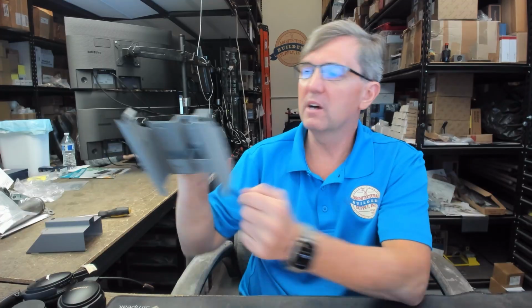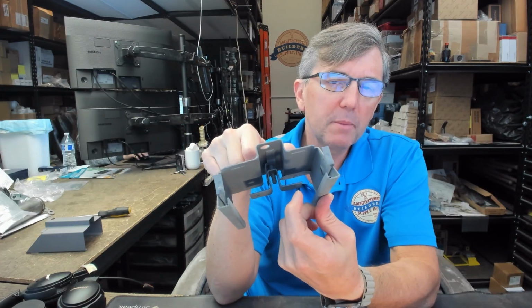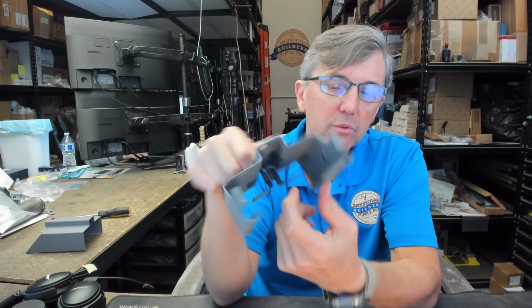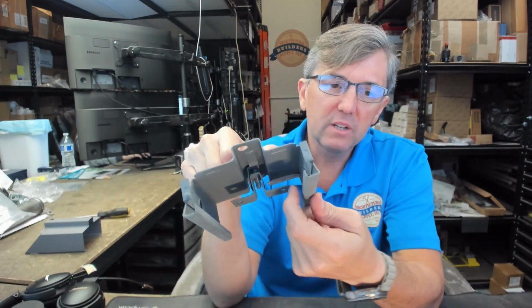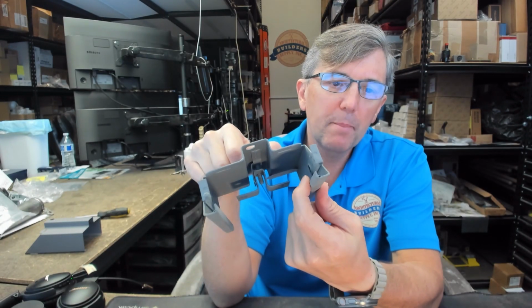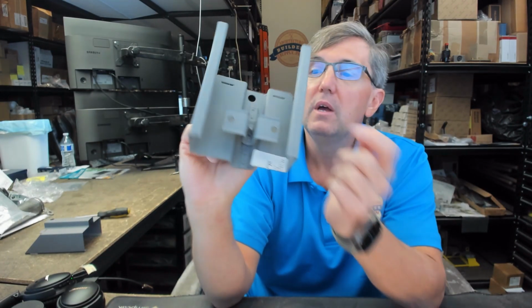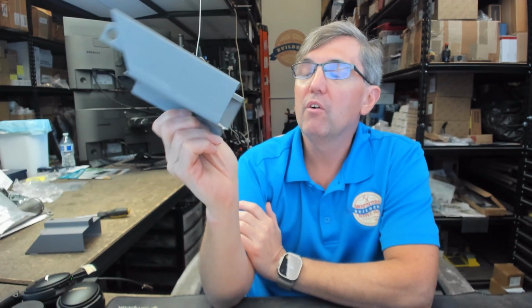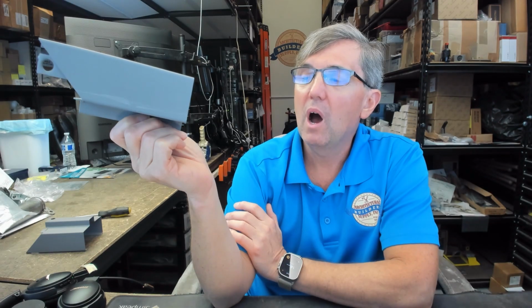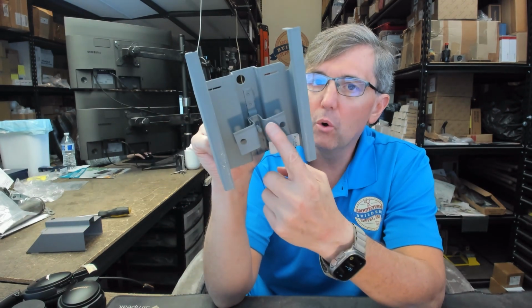Drywall frames can be prepped for all the different types of items that any other frame, masonry frame can be prepped for in terms of hardware, reinforced for material. When you're doing drywall frames, because of that back bend return, you're going to be limited as to what anchors you can use. You're not going to snap a T-anchor into this because that back bend return is literally in the way. So when you're doing drywall frames, you are pretty much generally going to see only compression anchors.